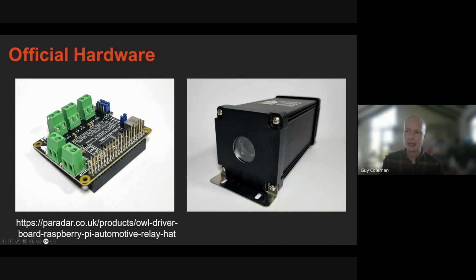And then you have the outputs here too. So each of these is a 12 volt, 2 amp rated output you can connect your solenoids to. So basically it combines it all into one. As I'll show you in the assembly, it simplifies a lot of the work required to assemble these devices. You just have a 12 volt input you can provide, which is quite straightforward.